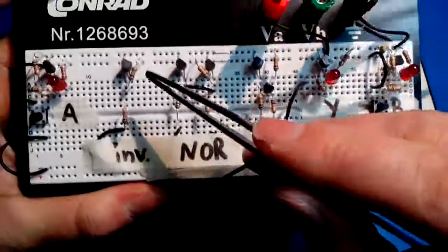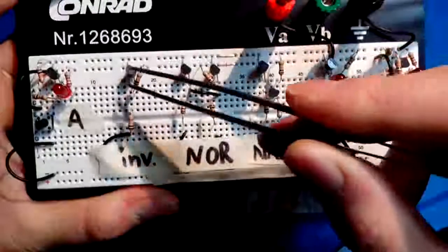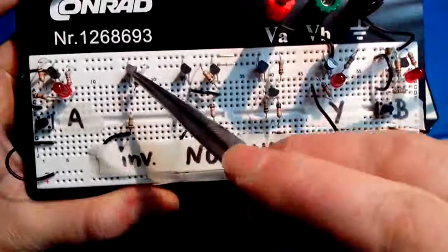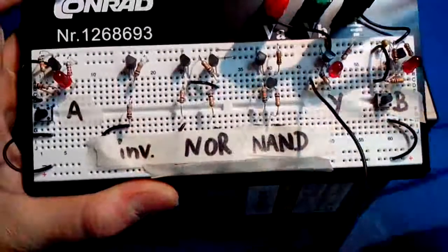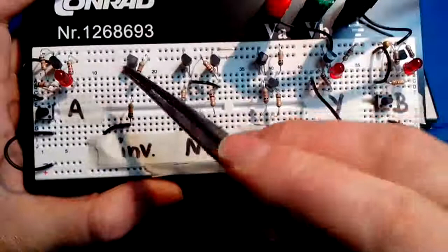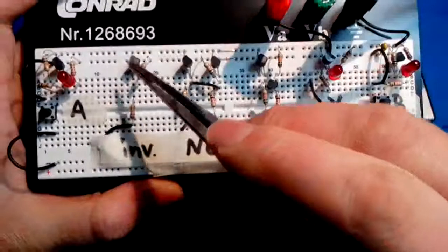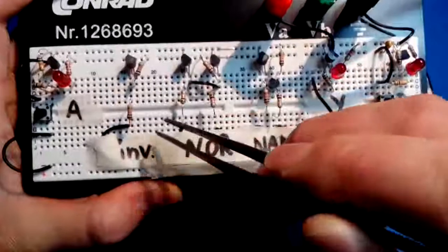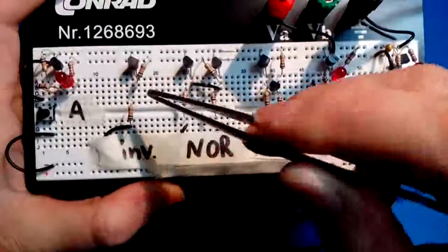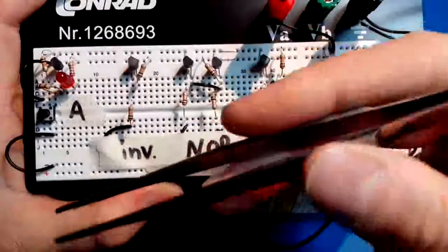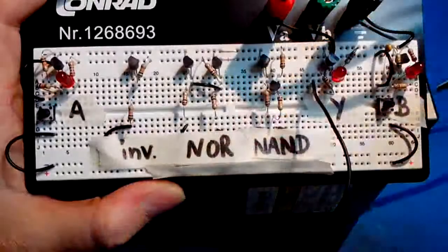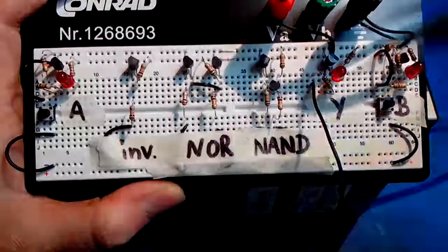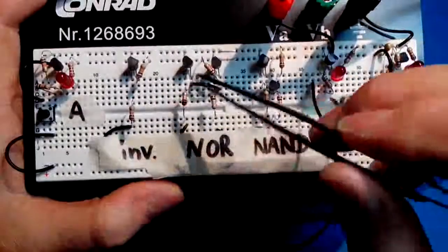There's an inverter, and you see on the breadboard we don't use SMD components for now, we use the BC547, which is basically the same as the BC847, except it's a different package and some different specs probably. The inverter only uses one transistor. Actually the value of the resistors, as you can see, is not exactly what we just calculated, but this is so small it doesn't matter. It matters if you make this 1000 times, but not 3 times.